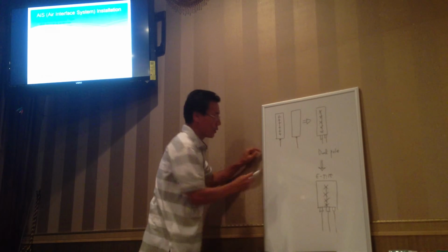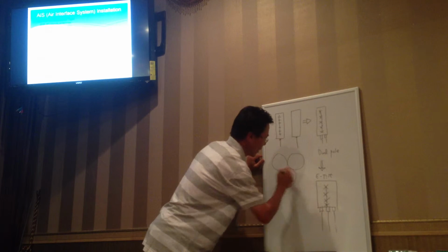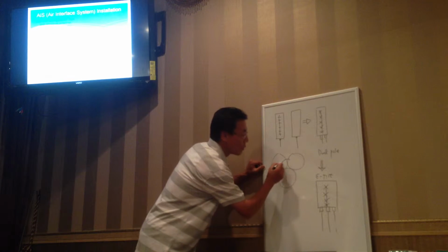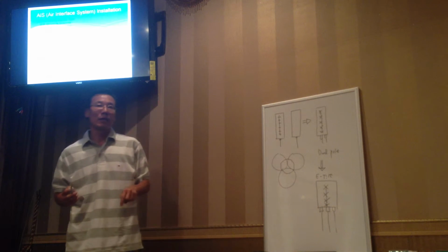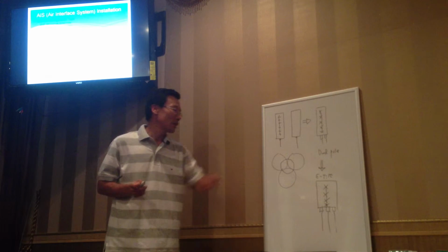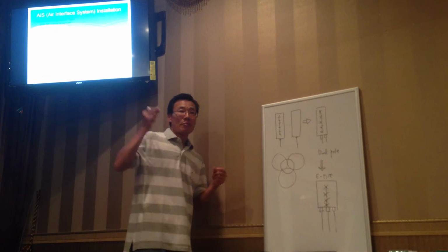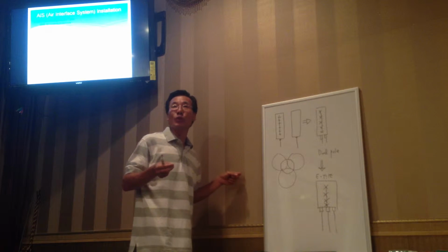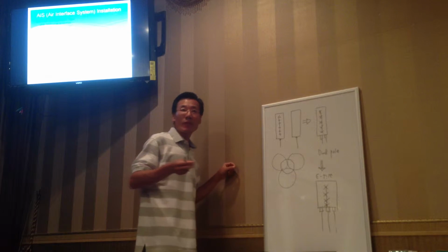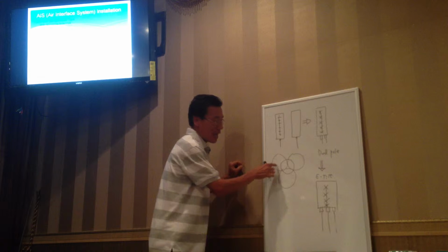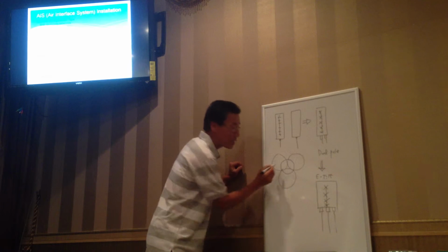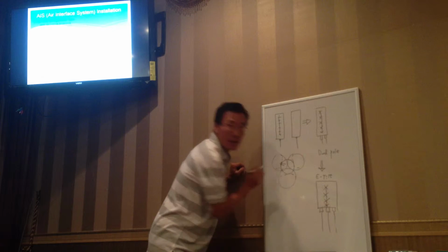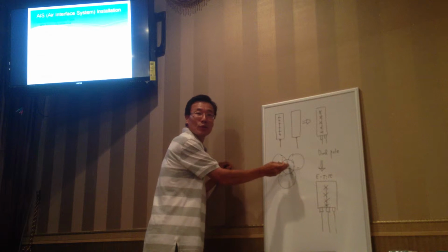They have a network, and when they have more customers, they need more capacity. They simply put a new cell here, right? And now putting the antenna here, there are two factors. The main signal I want to use we call the carrier, right? The signal we don't use we call the interference, right? So if they put this one in, now they interfere more. So what they need to do is reduce and adjust the coverage like this, right? To give room for the new cell site.